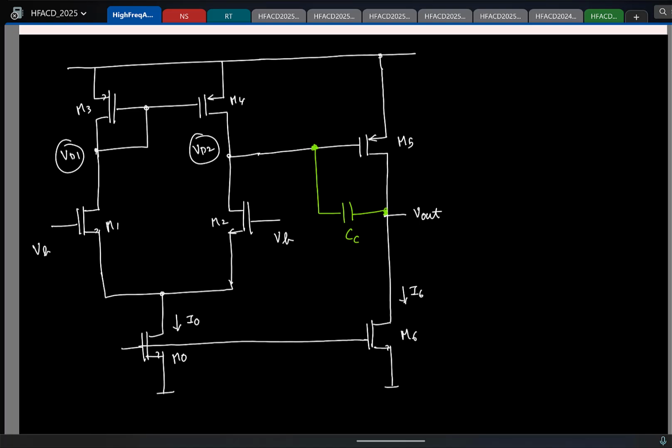Right. So here let's quickly figure out the positive and negative terminal. I know this is the output. How will I find which is positive and which is negative? Let's assume something. I'll increase the voltage here. What will happen to this drain voltage? Decrease. So the gate voltage here decreases. What will happen to the drain voltage? Increases. So if this gate voltage increases, output will. So is this inverting or non-inverting? Inverting. I'm increasing this, output is reducing. It's actually inverting. So this is the inverting terminal.